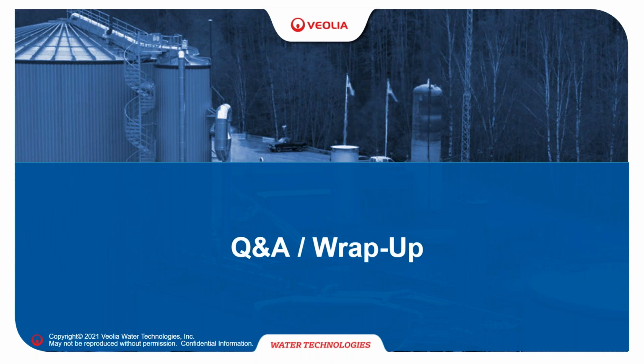I bet you do have biomass growth, but I'm guessing that it's washing out. I'm guessing that your effluent TSS is higher than your influent TSS, and that the sludge that you are growing is just washing out.